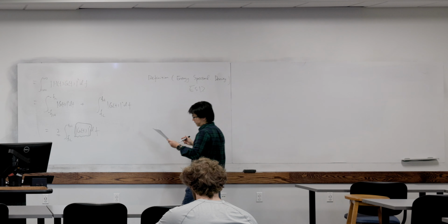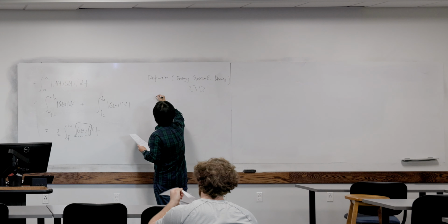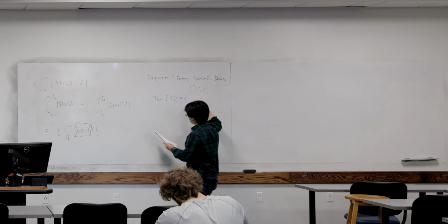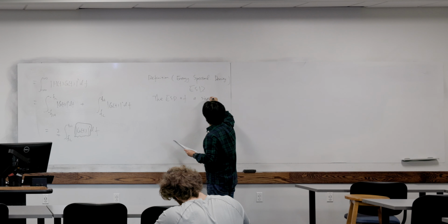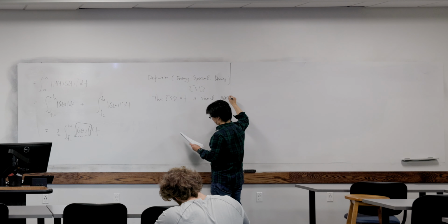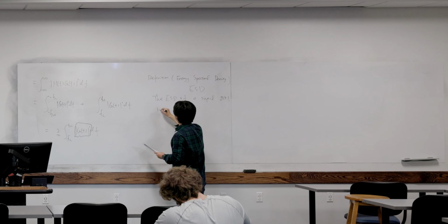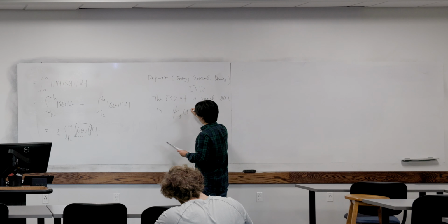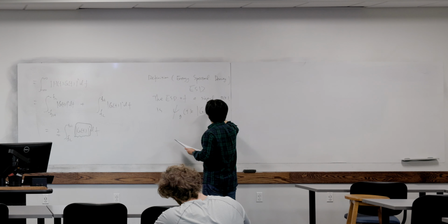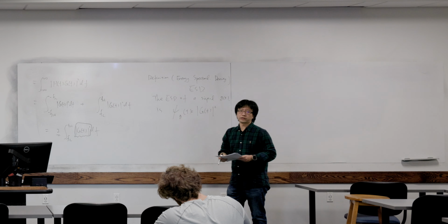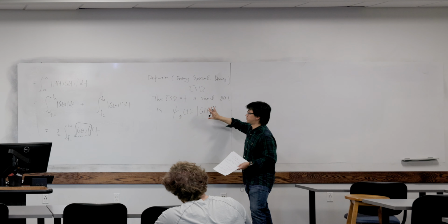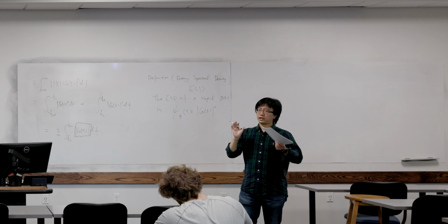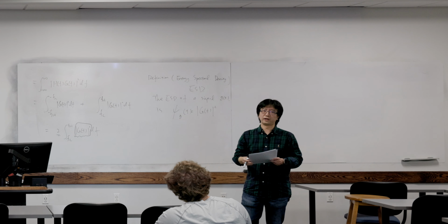The definition is: we say the ESD of a signal g(t), with the notation psi_g(f), is nothing but |G(f)| squared. If we integrate this over f, we get the signal energy for the specific frequency band.